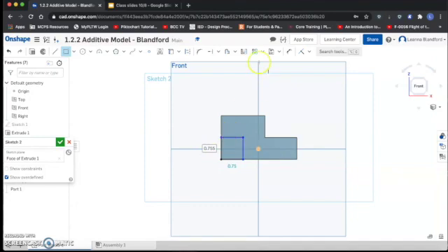Now this height is a little too tall because it needs to be exactly 0.75. So I'm going to redimension this to just 0.75. And now while visually we don't see a difference there, if we were to 3D print this part, it would make a difference. So now I've got that dimension to 0.75. And I'm going to change this to 0.75. And so now I have that perfect cube.